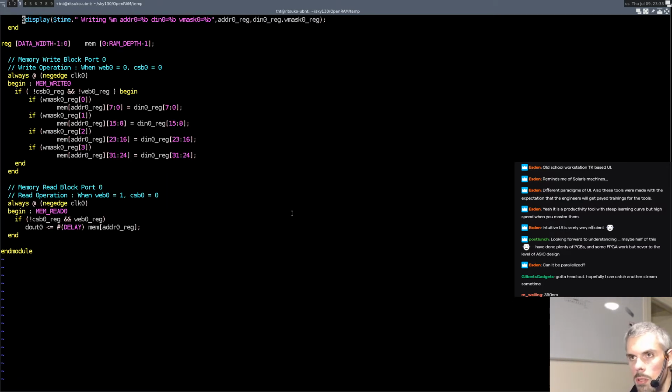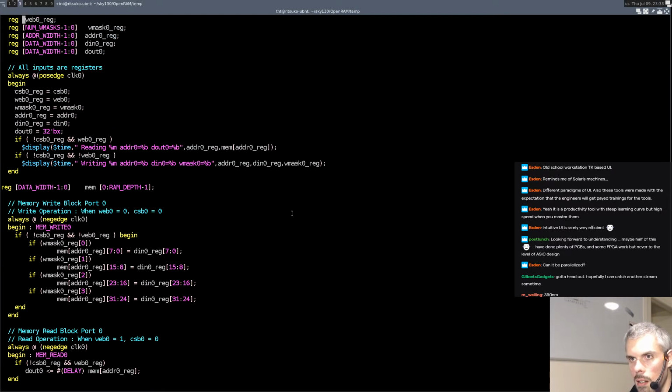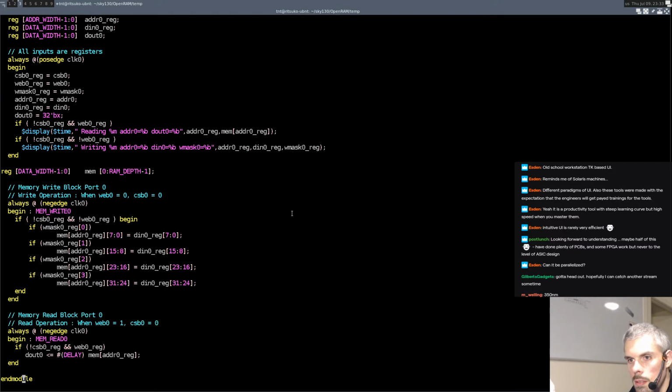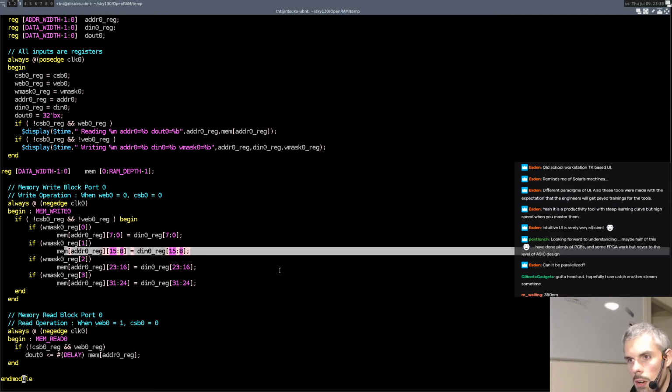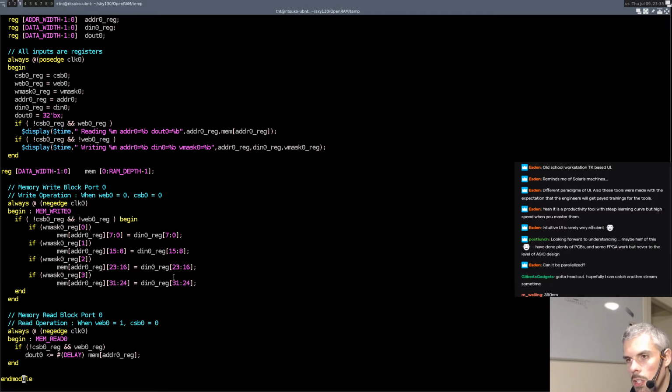Something to note, though, which is interesting in the kind of RAM that OpenRAM generates, contrary to what you will find in an FPGA: the clock to out is relative to the falling edge of the clock.